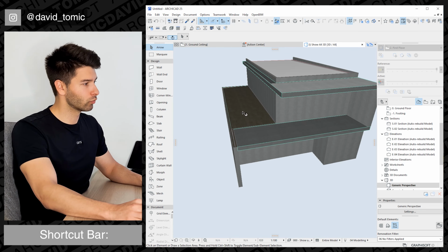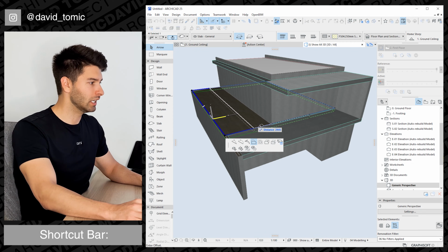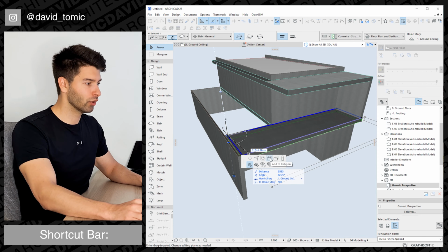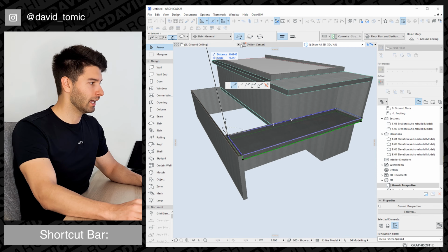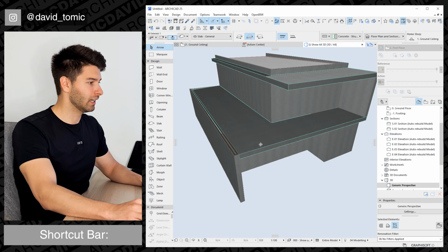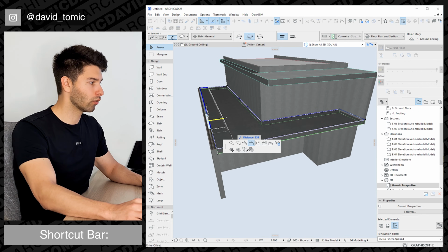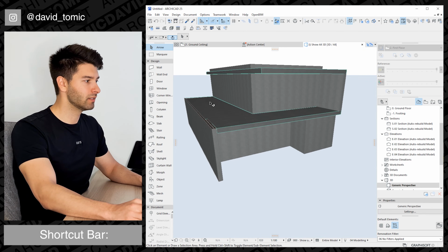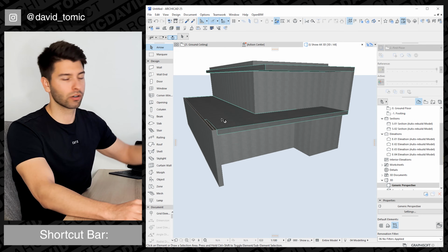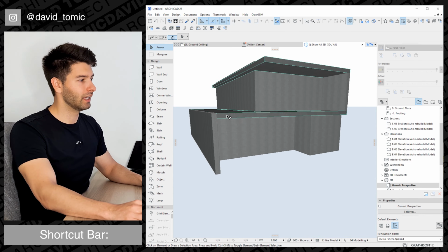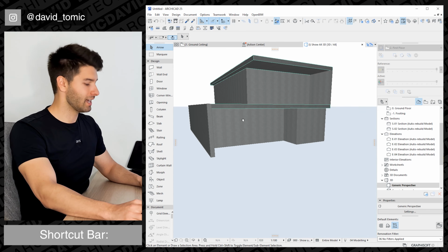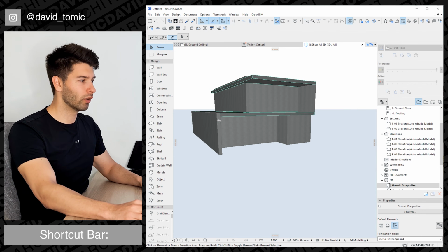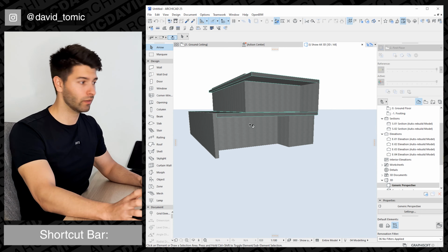Now, instead of creating an actual roof in this section, what I'm simply going to do is reduce that floor. Click on this floor here, go to our add polygon, and then simply extend our concrete roof across and extend our concrete roof back. So what we'll effectively do from a construction point of view is that'll be a concrete roof. We'll do a balustrade back there and hide that away so nobody can access that area. But that way we don't have to ruin and spoil the simple minimalistic design that we've created so far.